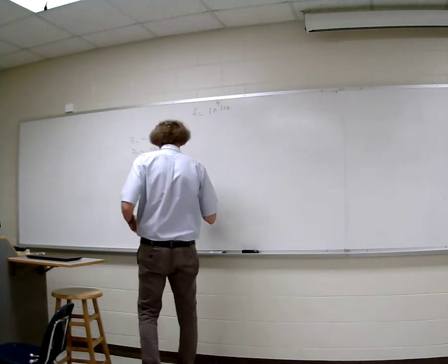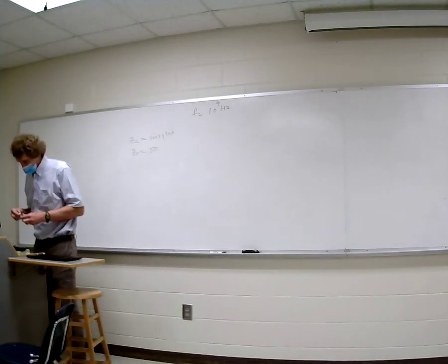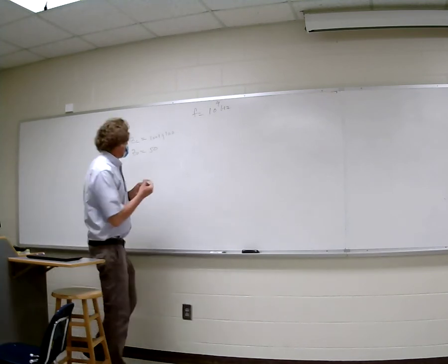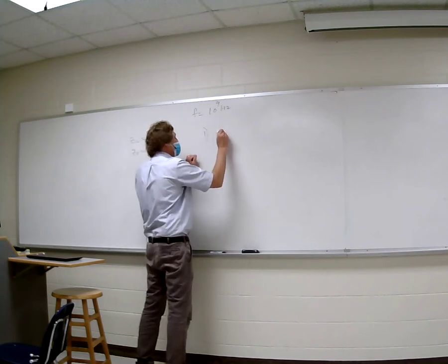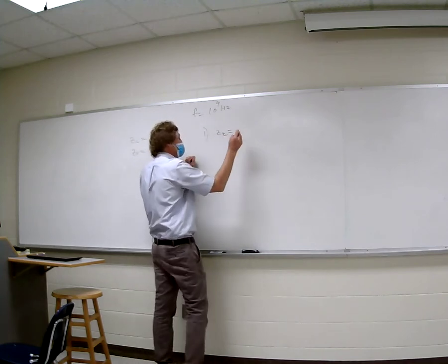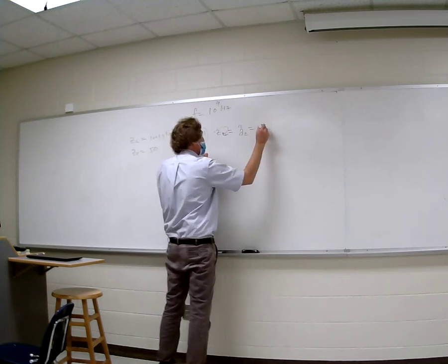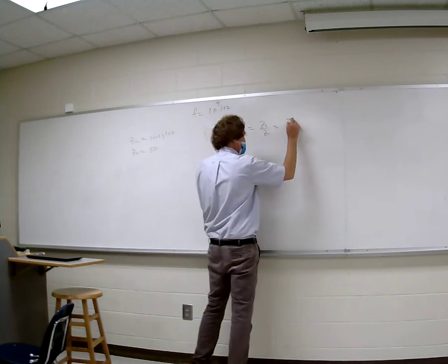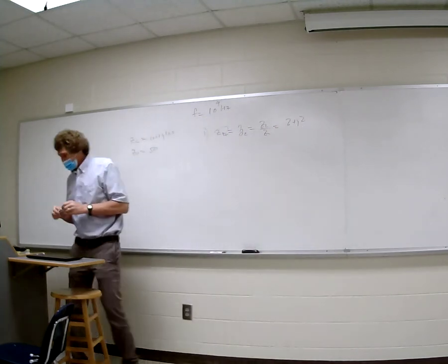So now, the first thing we do is what? We get the normalized impedance, the load impedance, and I'll call it small zL. That's just the load impedance over Z naught, and that's 2 plus j2, isn't it? All right, now it's 2 plus j2.